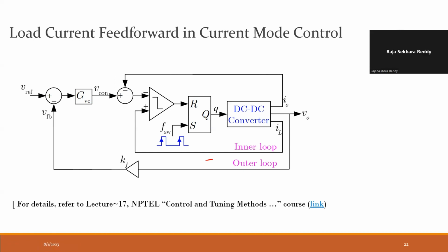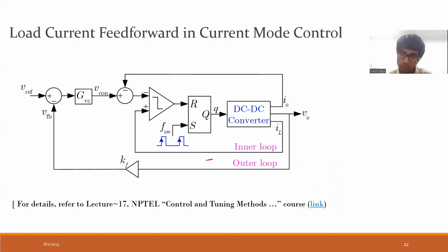Sir, you are saying this feed forward technique provides faster control than feedback? Yeah. See, what actually happens is that the feedback control loop is made slower. It is purposely designed to be slower, otherwise there are certain problems.